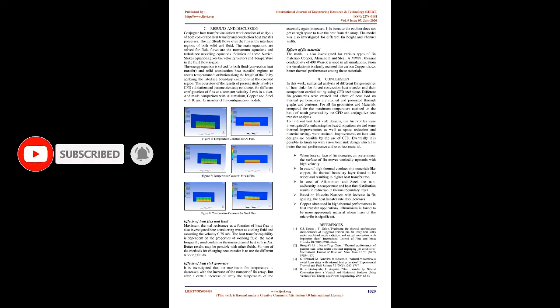The three-dimensional discretized model is generated in the meshing tool in the pre-processor phase as shown in Fig 4. The entire domain is discretized into finite volume hexahedral elements to capture the thermal and hydraulic boundary layers as shown in Fig 5, by very fine grids near the walls. A y-plus value of less than 1 is maintained near the fluid-solid interface to capture this phenomenon. The minimum angle and determinant of the hexahedral elements are maintained at 90 degrees and 1 respectively, which ensures very good quality of the finite volume discretization.